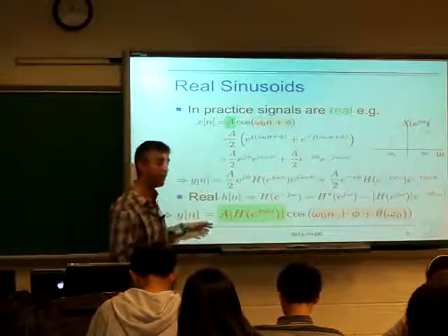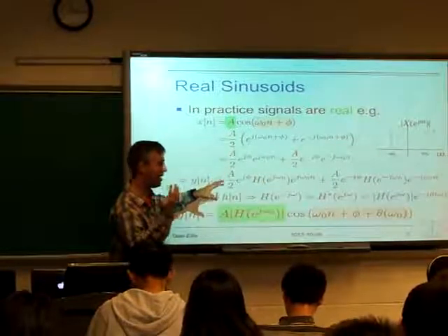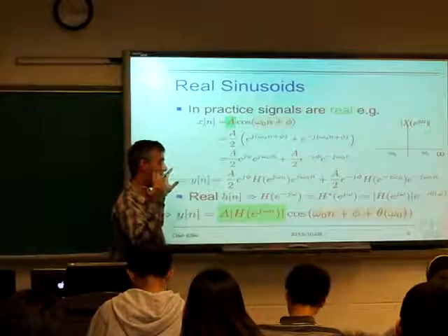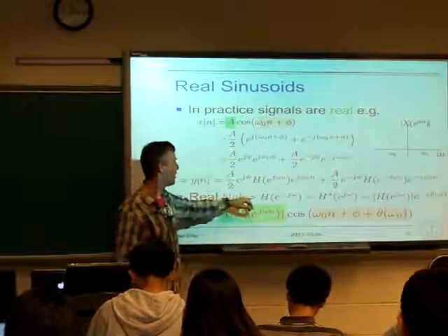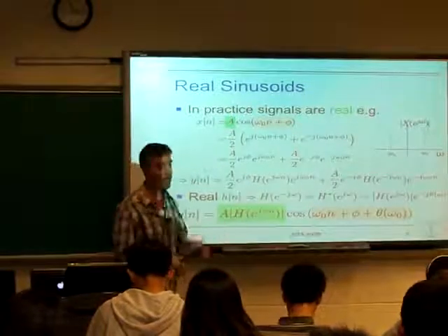We're just showing that because of the way it affects both the positive and negative frequencies, and for a complex conjugate DTFT, which is the DTFT of a real impulse response, we get exactly the same behavior.